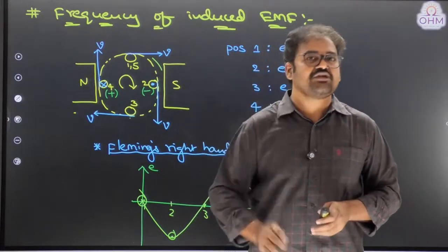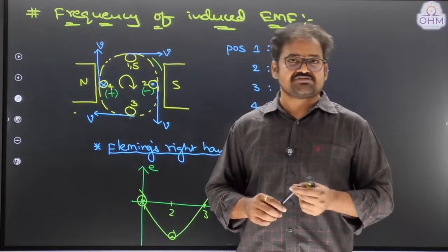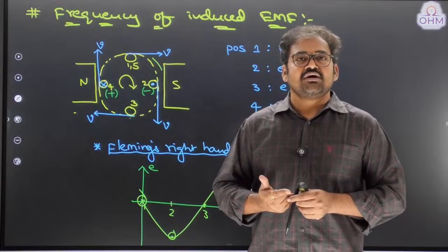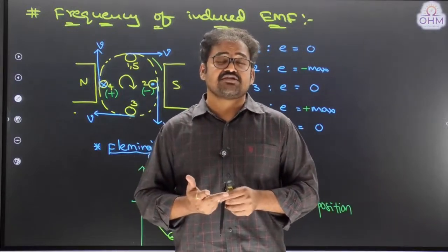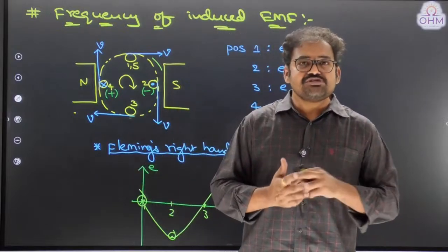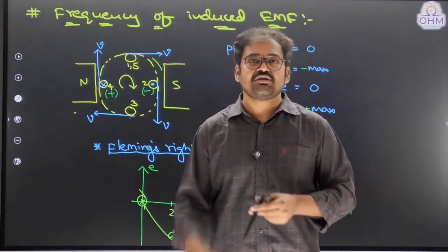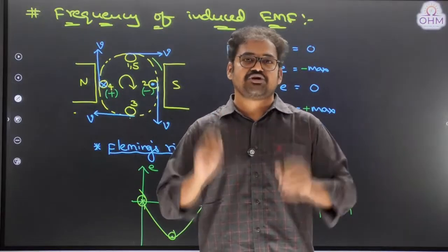Harmonics will always be involved, and to reduce those harmonics we have various techniques like short pitch winding, skewing of the conductors, using fractional slot pitch coils rather than integral slot pitch coils, and distribution of the winding. By using all these techniques, we can reduce the harmonics in the machine and we can make the output voltage almost like a pure sinusoidal waveform.